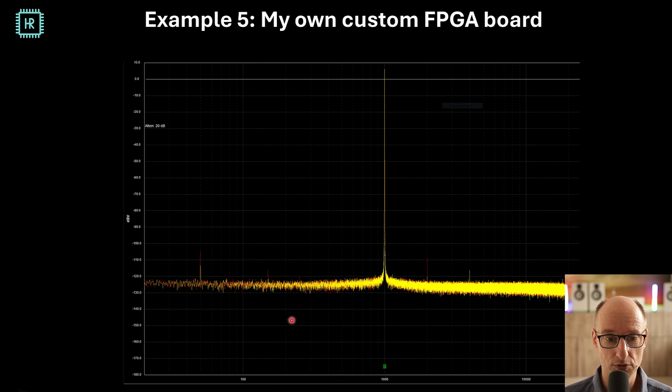But as you can see with the result, this is the total spectrum. You can see how incredibly clean it is. You see some 50 Hertz harmonics here. You almost cannot get rid of those because the grid runs at 50 Hertz and it's everywhere. And you see a little bit of distortion, but for the rest, it's completely clean. So here you can see the huge impact it makes when you specifically design a board for good ground and RF performance. And even though this is an audio product, which is low frequency, you still see the huge impact it has.